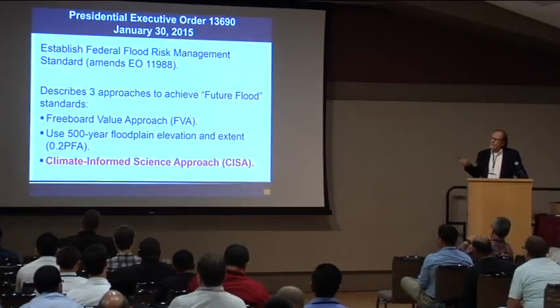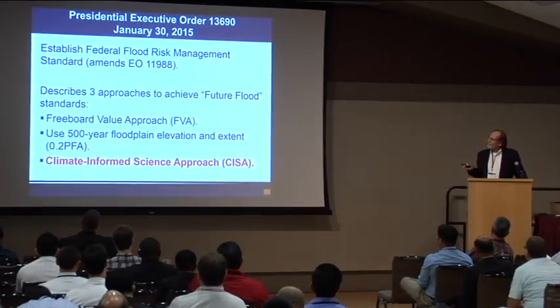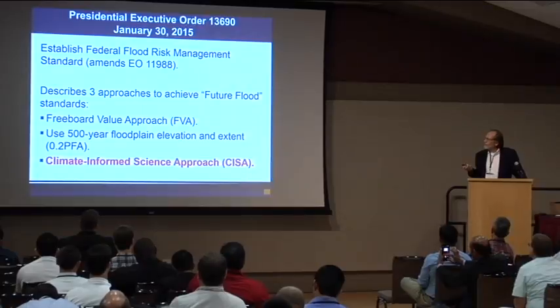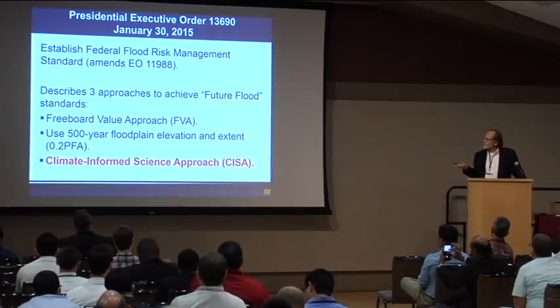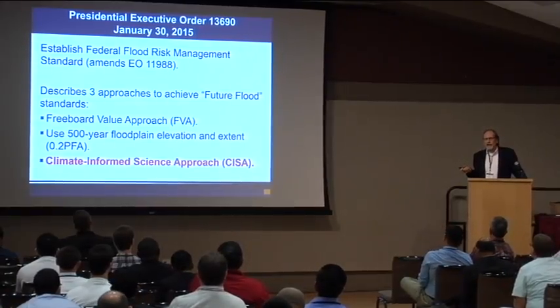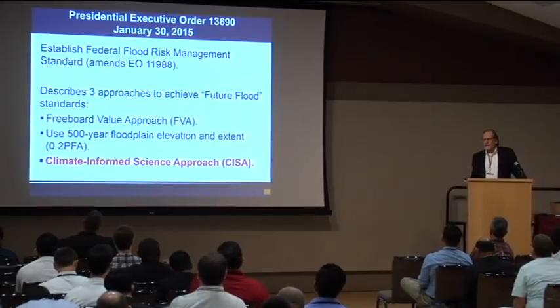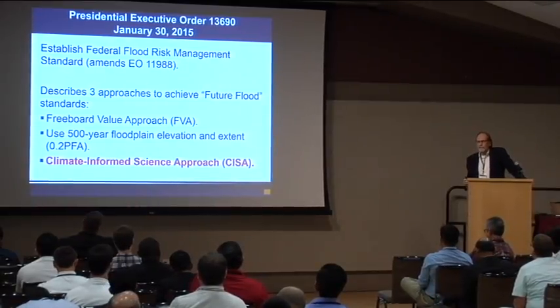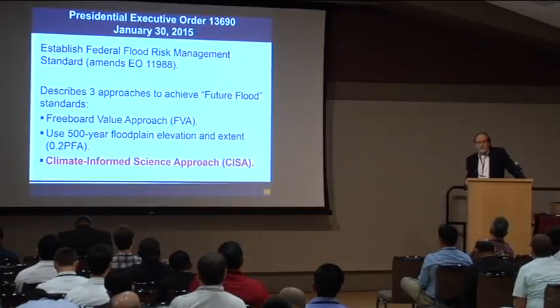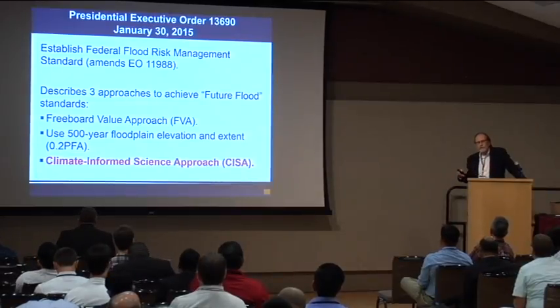Like I said, these other two approaches, and in fact, I think the executive order seems to be written in a format that it was kind of for structures like commercial buildings and residential buildings. We don't really think, and this is my opinion at this stage, that these are actually applicable to roadway design and bridge design. And you think about it, it wouldn't be, because we have a lot of bridges, of course, that are designed for overtopping. We also have, as I mentioned in the sheet flow analysis, roadways that actually convey the extreme event stormwater. So why would you base those roadways off of these freeboard approaches?